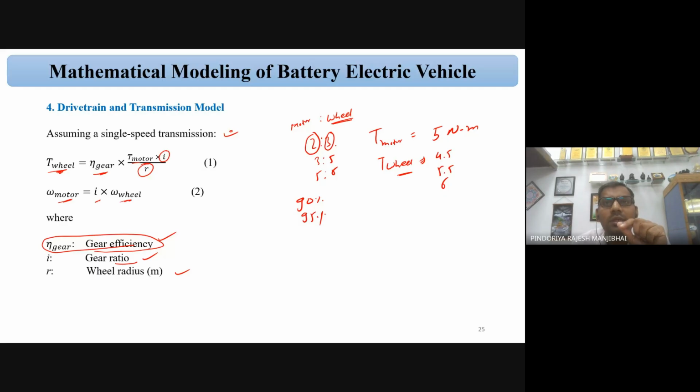In the BLDC motor, how we operate it I already discussed in the first semester, I think. We have to sense the rotor position, correct? Suppose this is your rotor, and the Hall effect sensors are placed here, here, and here, normally aligned 120 degrees to each other. So we have to sense the rotor position.